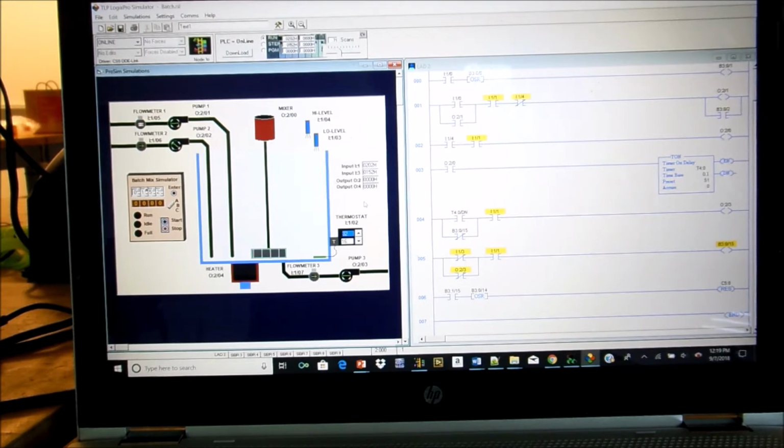Now, when you do it with Wonderware, you have to come up with some simulation software as part of this. So when you turn a pump on, you have to simulate the flow meter with some timers. You set up a really short little timer that goes pulse, pulse, pulse, so it can count up the number of fluids from this one and this one.